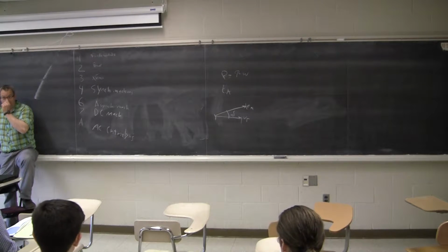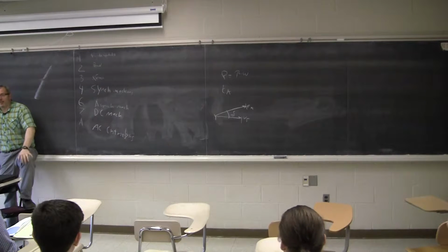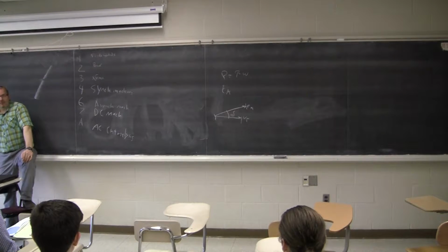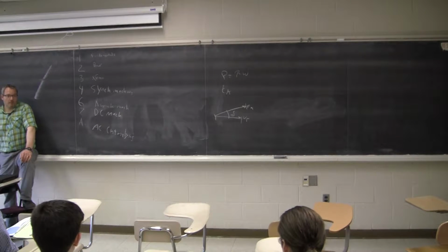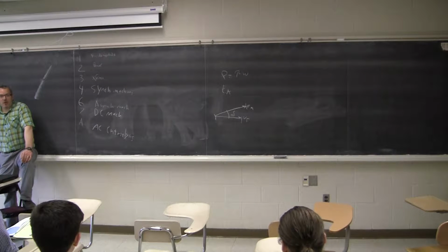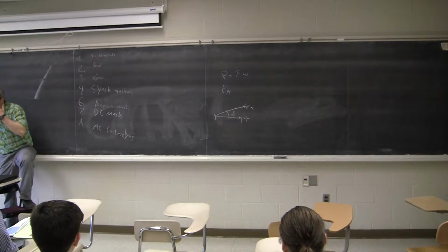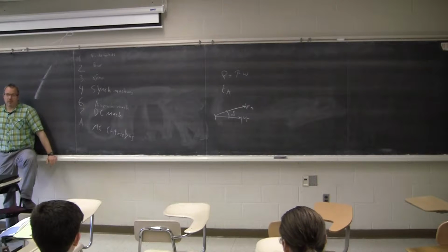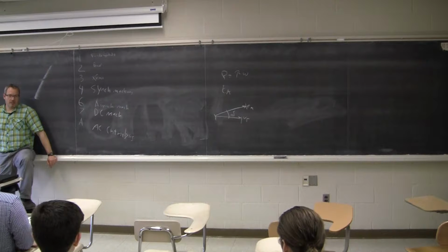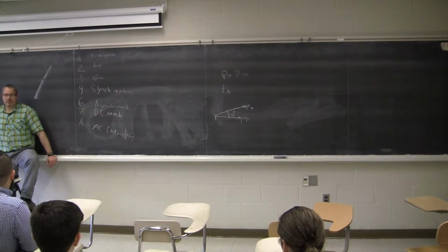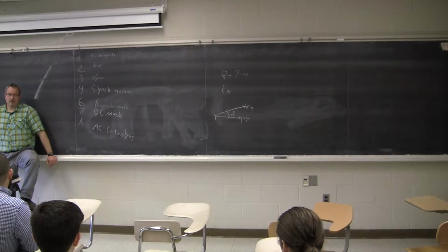So it's almost like a synchronous machine, but you don't have a separate field. It's all done by a permanent magnet. The Tesla uses an induction machine. I don't know of any vehicles that are pure, maybe purely electric like the Nissan Leaf or whatever, but the most popular hybrid car, which is a Prius, most people would say is probably the most widely accepted electric or partially electric vehicle, uses 3-phase AC machines. Nice smooth torque, nice way to go.